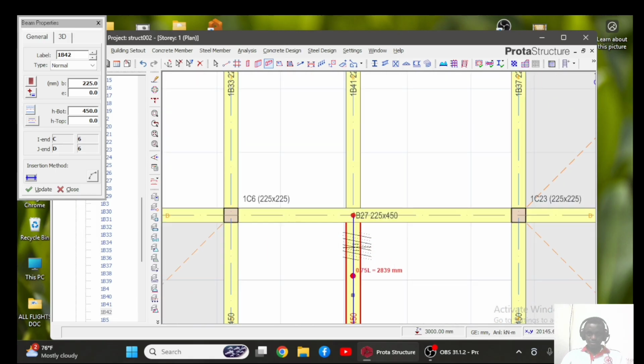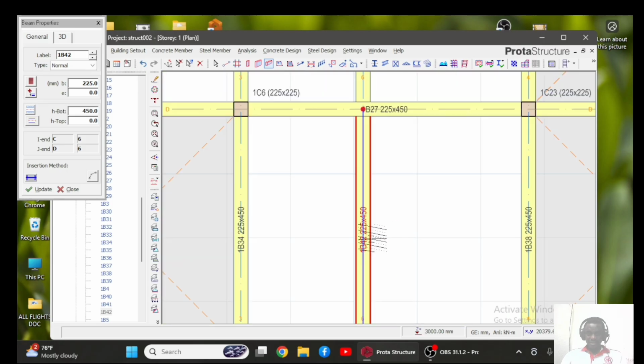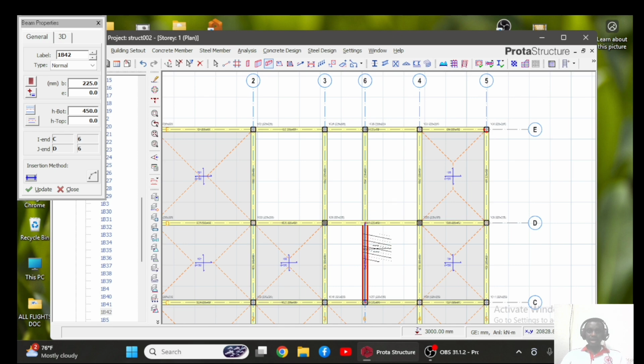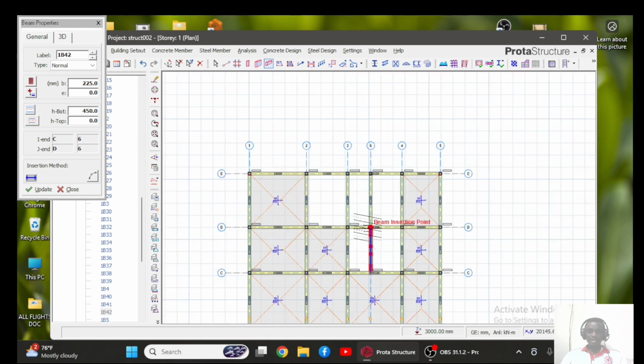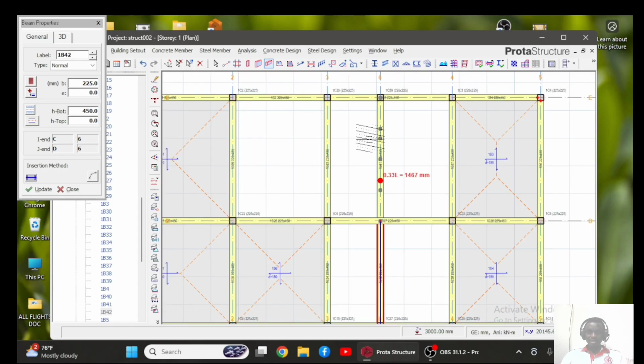At this point the beam has been broken in such a way that it passes through this other beam 27, and then at this end it forms a new beam 42, rather than what we had in the first instance. In the first instance, the whole thing was beam 41, meaning the beam overlapped. It went all the way over this one, which is very wrong.